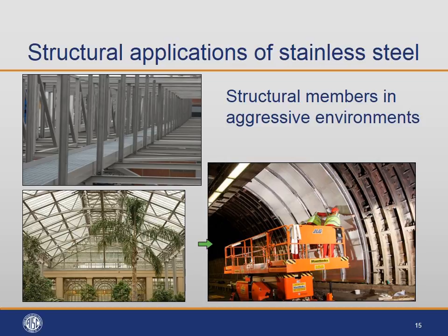And my third photo is in a tunnel. Highly durable materials are needed in corrosive environments that you would find in tunnels. Maintenance is very expensive, and of course there are very severe consequences of a structural failure or fire. So stainless steel might be used for supporting the lining or framework or maintenance walkways and fittings and fasteners.